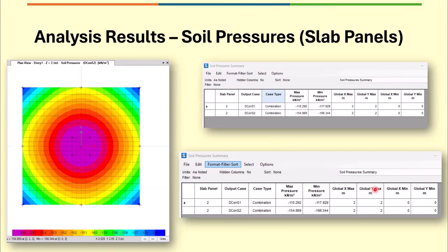And for soil pressures, typically we'll check for the limits, and we can get those outputs in terms of graphical output. We see in this picture that will also show you the minimum and maximum with contours. So quickly understand the behavior or the response of these soil pressures, whether they are under compression or any tension is existing. This is from a linear static case. All the values are negative, the minima and maxima. That means it's under compression, no tension exists.